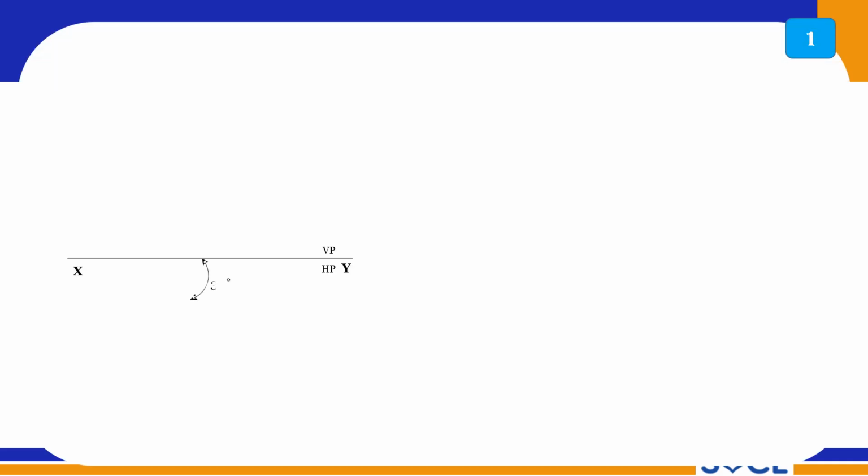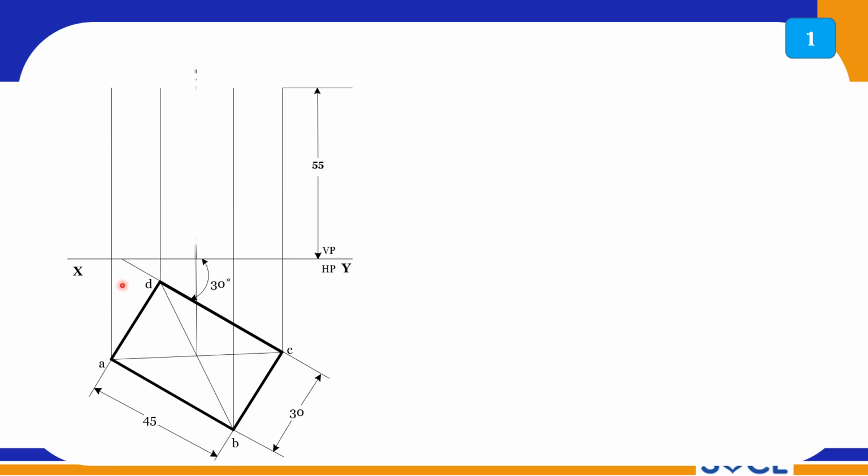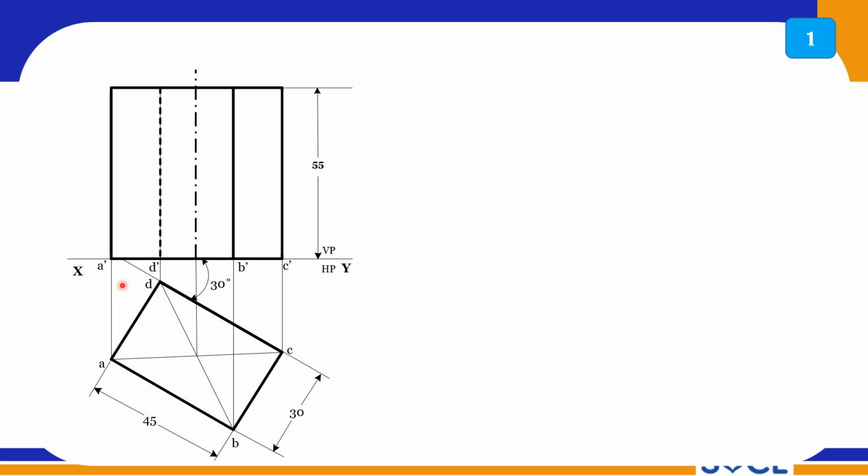So first draw the XY reference line, and at 30 degrees you draw a line. On this line you draw the rectangle of the given sides, so that is 30 mm and another side is 45 mm. So the longer edge is making 30 degrees to VP, and height is 55 mm, and draw the rectangle front view. So this is the front view of this prism. You know how to draw this front view, right?